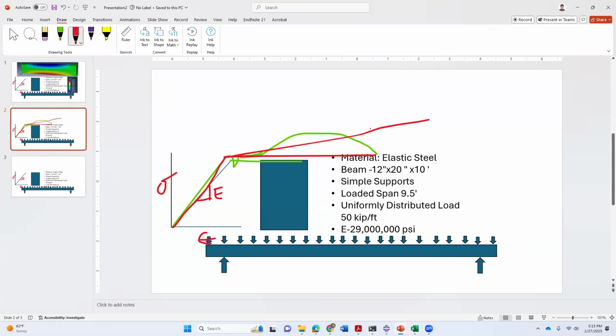increasing plastic displacement. But for modeling purposes here I am using a linear response up to the yield point, which will then continue at the yield stress as long as it does not fail, and we know it can still fail at 28% of elongation, depending on the grade. If you have higher grade, it will still fail at maybe even 8% or 10% strain.